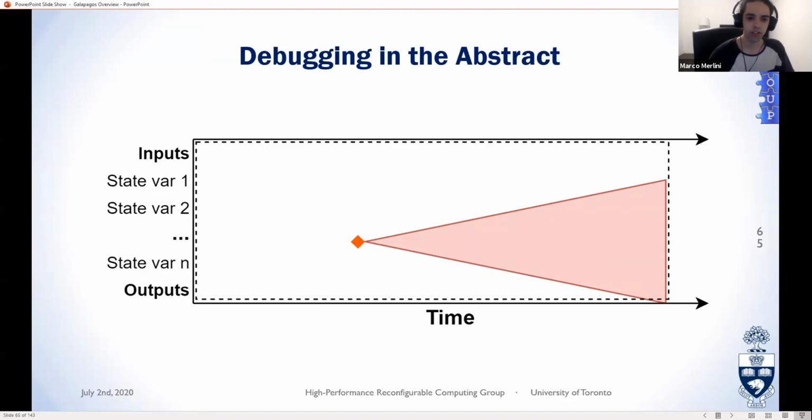Of course, simulation fixes the search problem. I can see the entire search space. And simulation is a necessary but not sufficient debugging tool. Writing test benches is difficult, time-consuming, and error-prone. And it can be difficult or impossible to recreate the exact conditions of a bug in simulation.